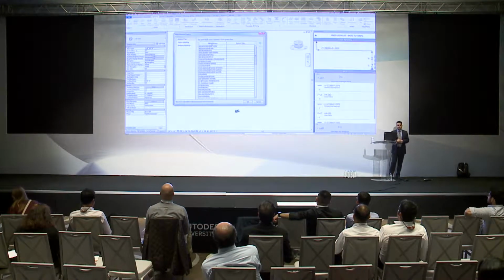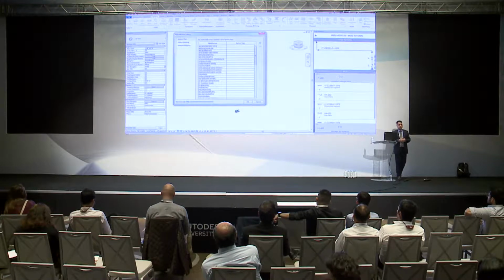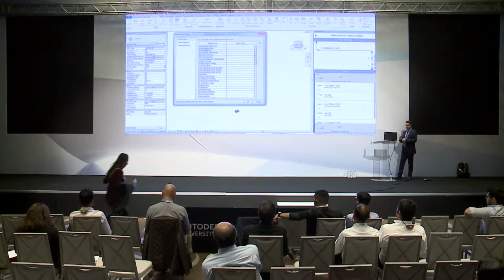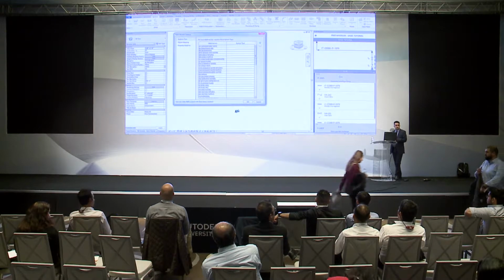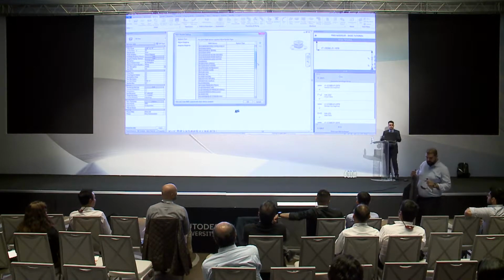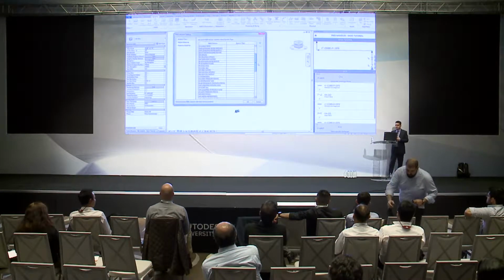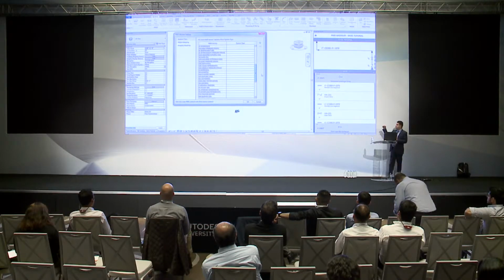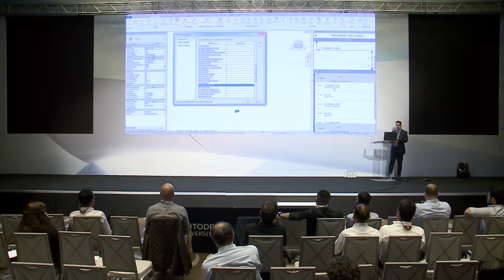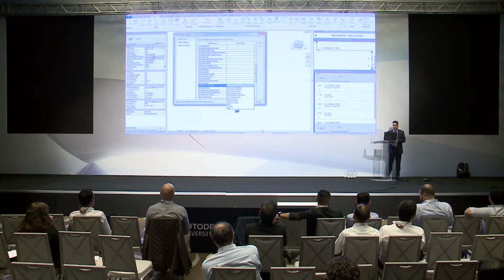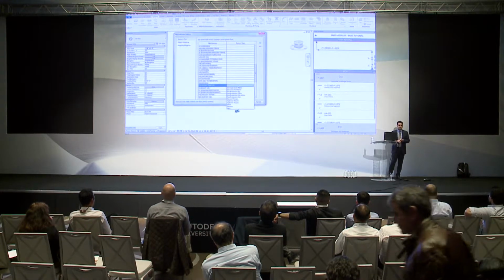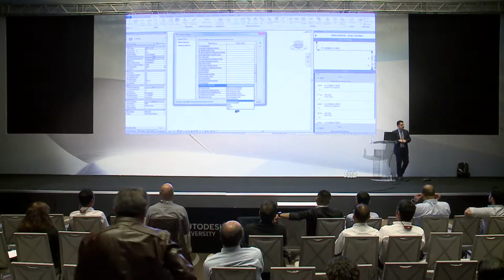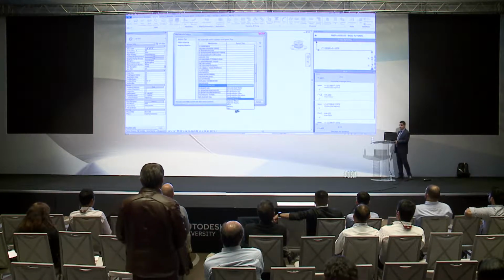Now, apart from that, when we start our project, we can say which is the service coming from schematic, and which is a service I'm going to map within the Revit environment. So you can say, for example, chilled water pipe coming from schematic will be mapped to a chilled water service inside Revit MEP here. And similarly, if you want to map the equipment like chillers, pumps, and all those kinds of things, you'll be able to do the mapping as well.